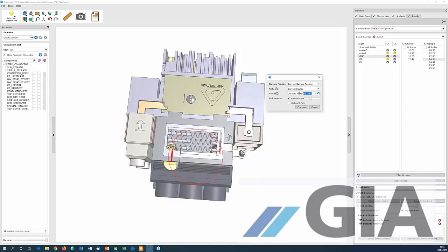By default it's the assembly view, because the basic application you want is to override the current default assembly view with the new computation. This is done by just using the same name, and then the old ones will be overwritten, but you can also choose a new name, and then the old ones are still there and the new ones are added to the list of camera positions. But in this case we want to override them.